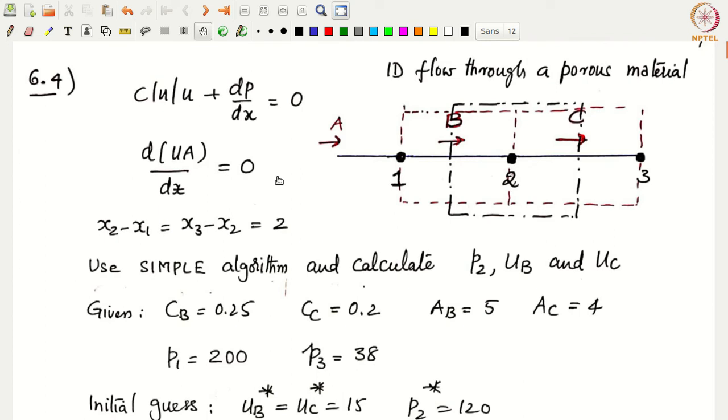Okay, so in the last lecture we looked at the overall SIMPLE algorithm on a staggered mesh, and we also considered the effect of under-relaxation for pressure and the momentum equations, and finally we looked at the velocity and the pressure boundary conditions when solving any problem using SIMPLE, right?